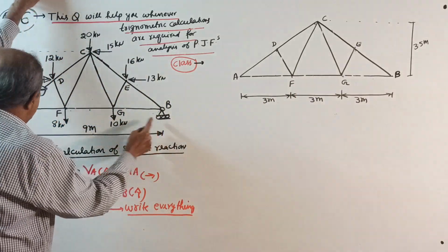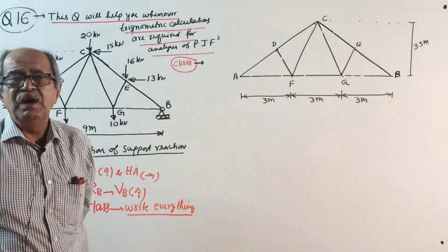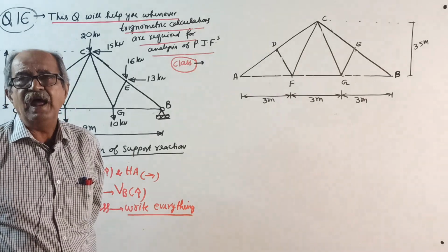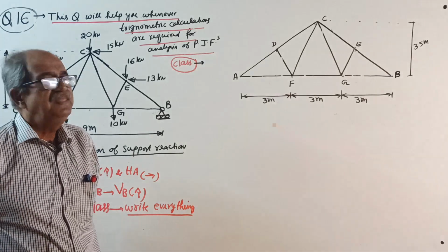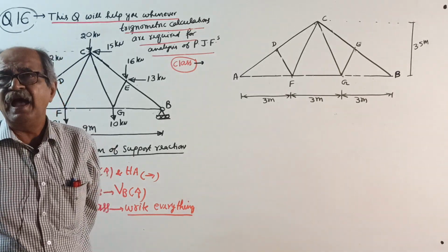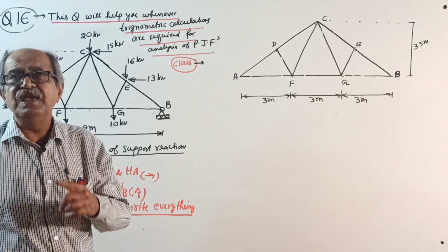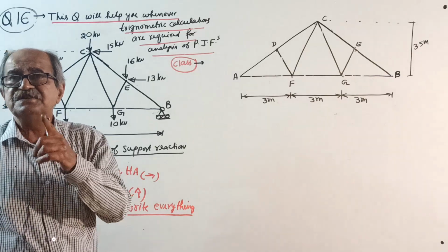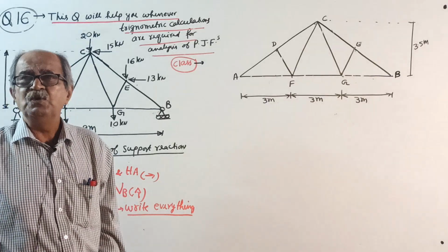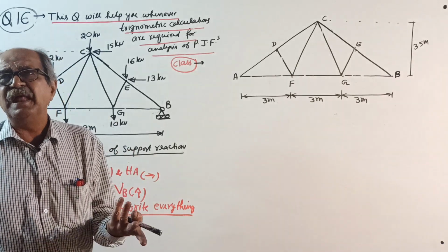Then apply sigma M equals 0, sigma V equals 0, sigma H equals 0 and find the reactions. Then usually for the inclined members, you find the angle. Then you draw a neat sketch. I used to call it the star sketch. By this time you know it. And then enjoy the method of joints. Now it is so mechanical.